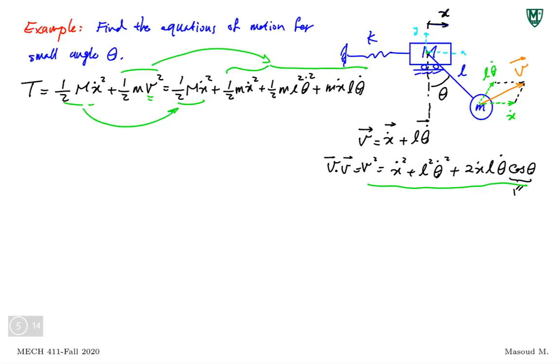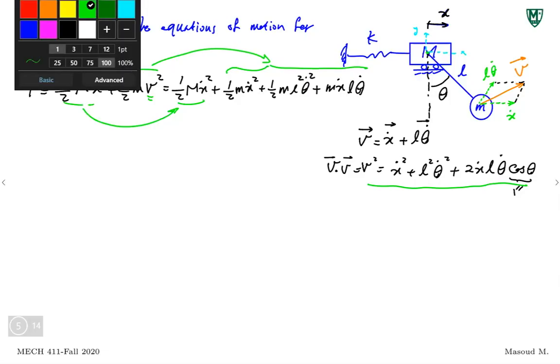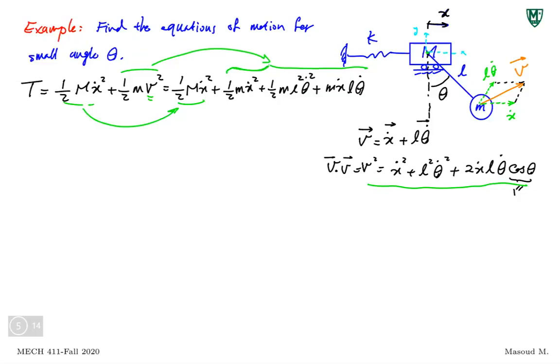If this is the case where you're assuming the pendulum is translational and rotational, because it's rotating and translating at the same time, right? It has a horizontal motion because of the motion of the car, and then it has rotation around the point that is attached to the car. If you look at it as a translational plus rotational system, you can just calculate the kinetic energy that way. You should get the same expression as here, right? This expression right there. These three terms.